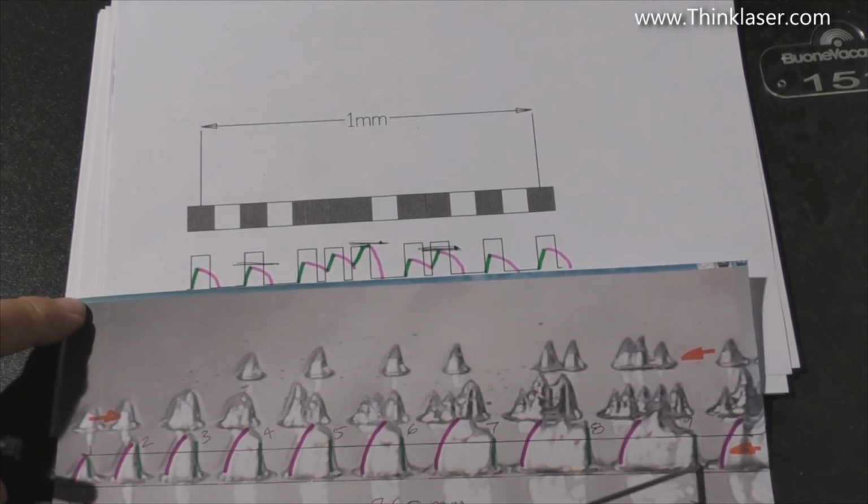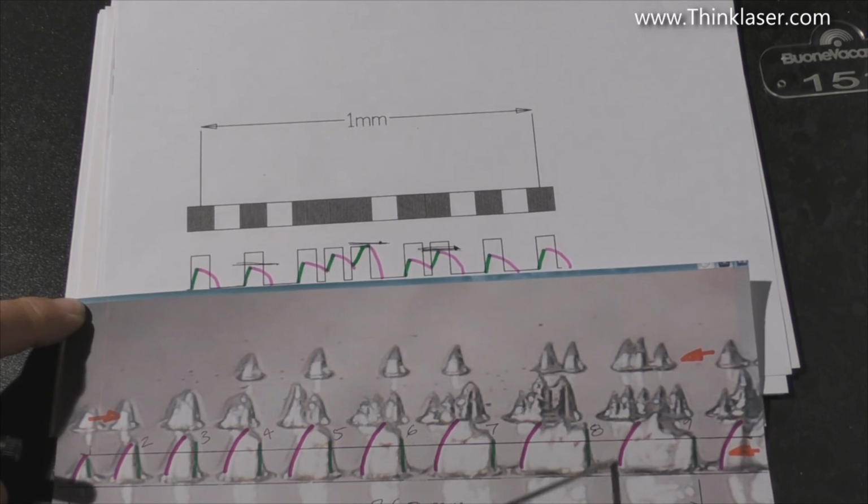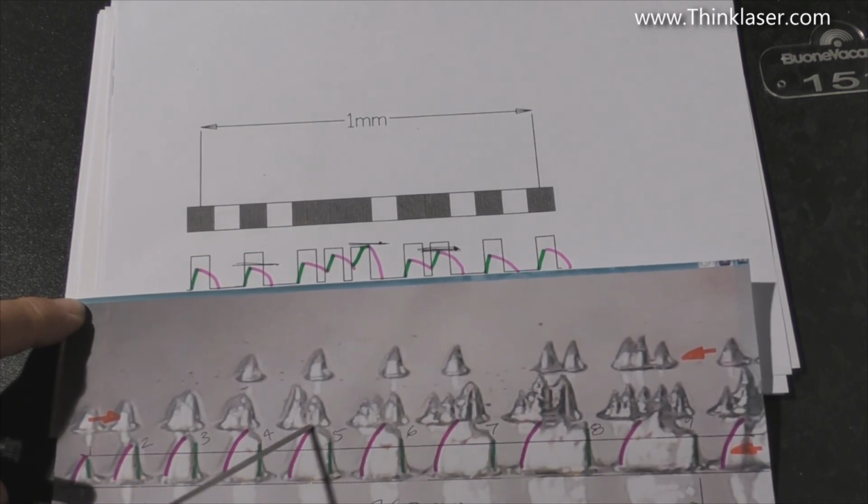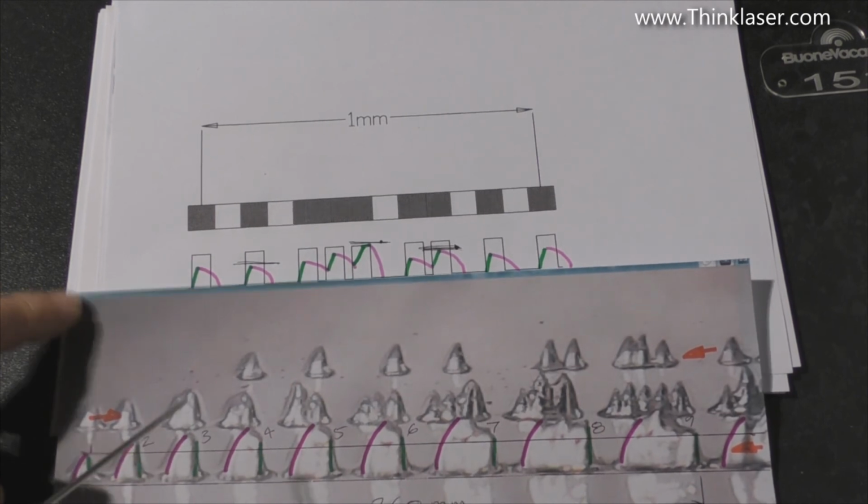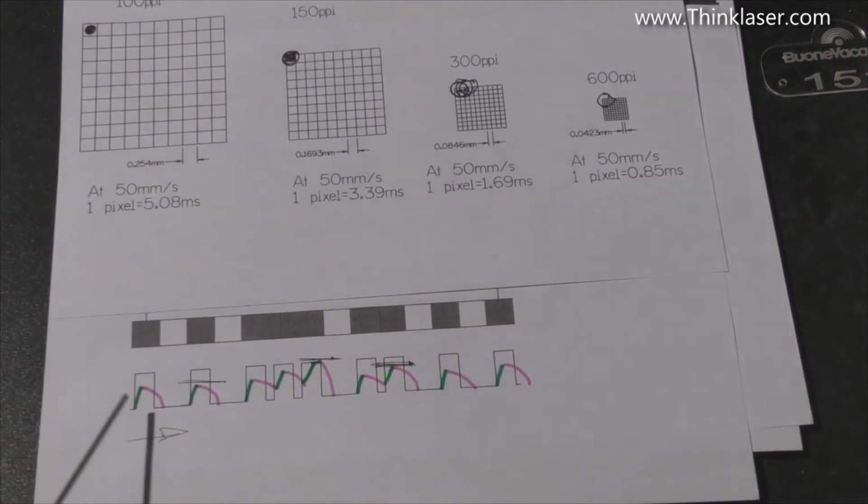Green is the beam on, and pink is the beam switching off, and you can see how much drag or lag, delay time there is in switching the beam off. The beam switches on, and it never makes it to this maximum that we were trying to go for, the maximum power. Why not? Well, because it has to switch off, and it takes a long time to switch off, so therefore it starts switching off early, and it never makes it to this maximum position.